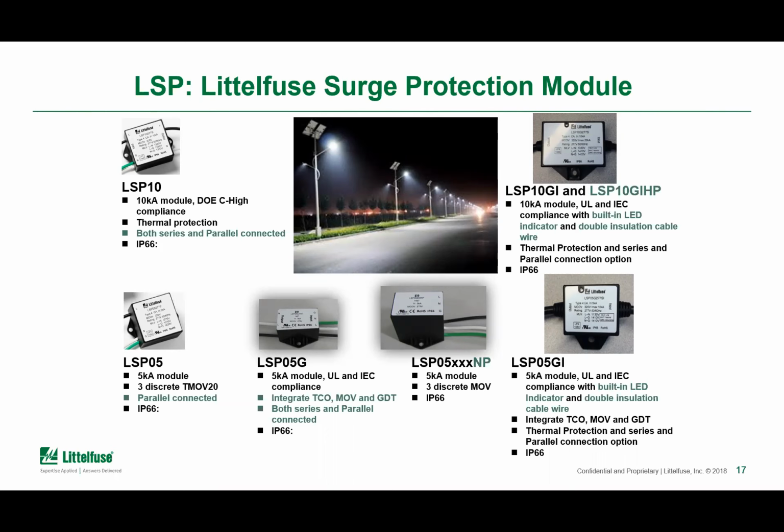And then finally, there's our LSP10GIHP, and HP stands for high performance. What we've done with this device is we've added in some additional components that reduce the amount of let-through voltage that is seen by the driver. So it actually provides a much higher level of protection, better level of protection for the application or for the fixture itself.